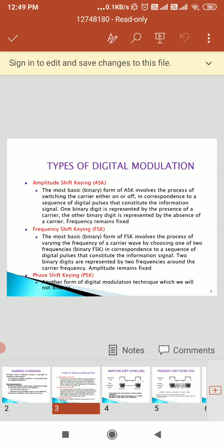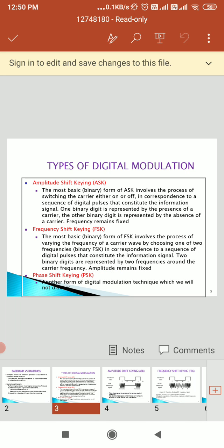If we are doing band pass modulation, it can be used to separate different signals over a single channel. So here we see different passband digital transmission, because passband digital transmission allows more efficient use of the allocated bandwidth and flexibility in accommodating different baseband signal formats. We can take examples like mobile telephone, GSM. Now we are supposed to see the different types of modulations.